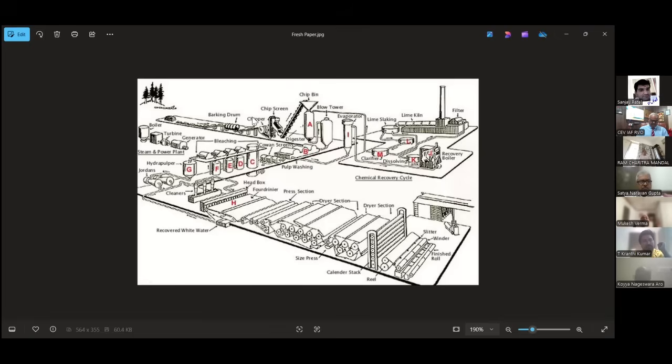Okay, the chipper cuts it down into small chip forms. Then from the chipper it goes to the chipper screener. It is based on the size of the chips. It is a grading. Small or required size chips are taken out for further reactions, and whatever higher size chips are sent back to the chipper machines and cut down further. From the chipper, it goes to the digester.